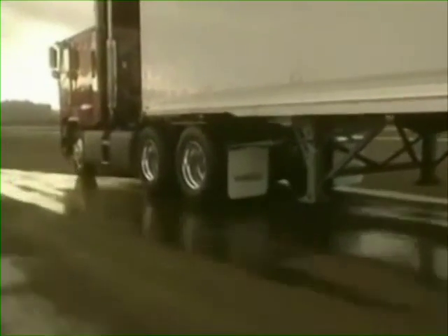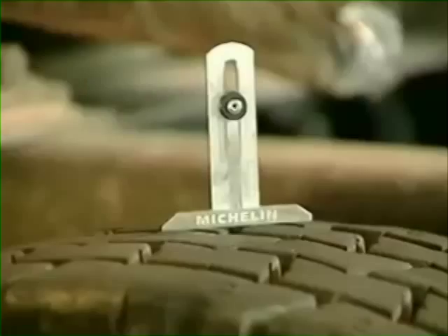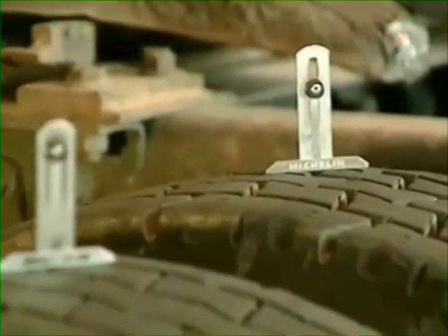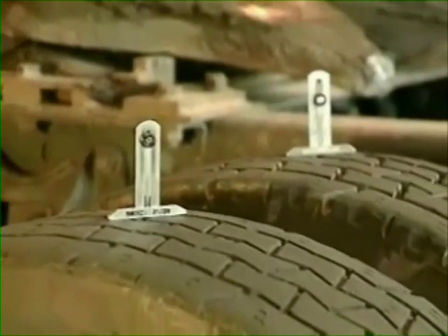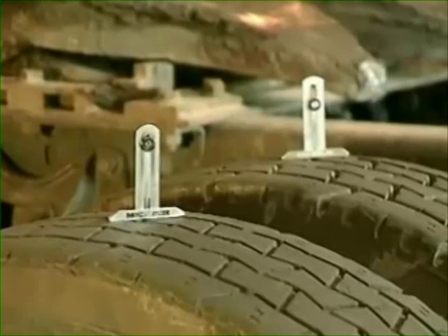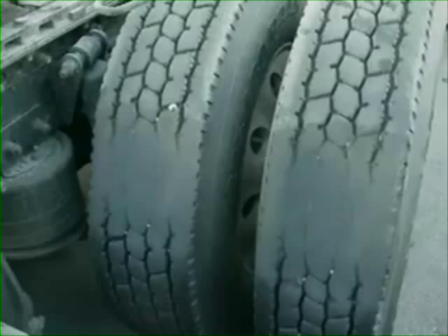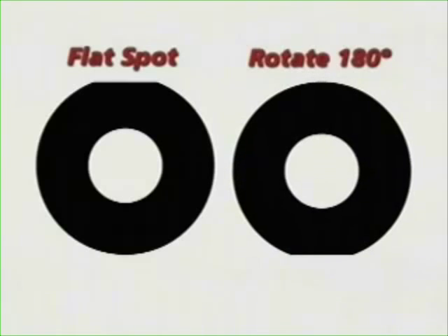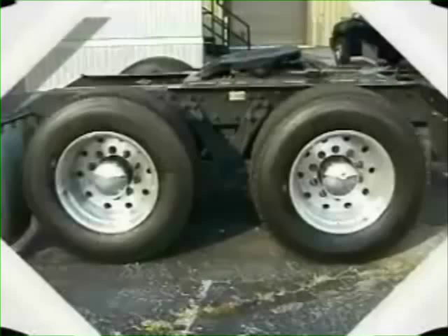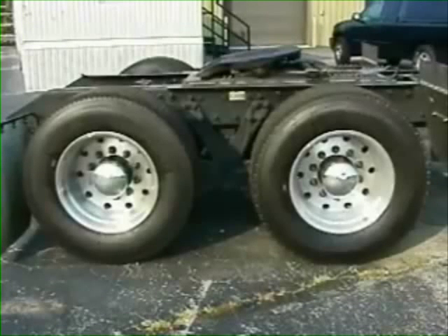If the vibration appears to be coming from the rear end, check the rear tires for mismatching of duals. A difference of over 4/32 in tread depth may exist. If a set of dual tires have flat spots in the same place, rotate one of the tires 180 degrees to reduce the harmonic effects of the flat spots by allowing them to cancel each other out. Generally, rear tires do not need to be balanced.